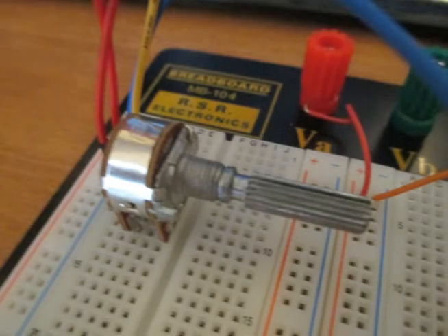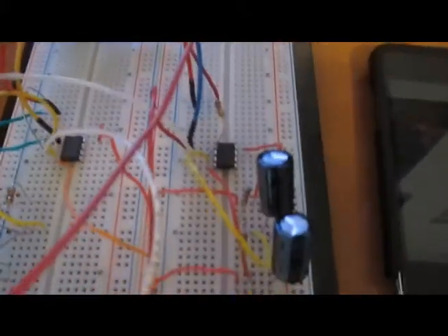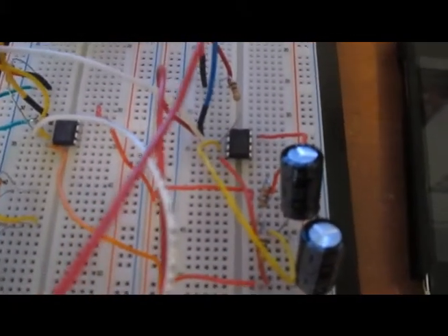This is the potentiometer used to adjust the gain. We used a 50K potentiometer in conjunction with a 10K resistor to avoid overly touchy gain. Here's a closer look at our circuit. We used two inverting op-amps, one for the left audio and one for the right audio.